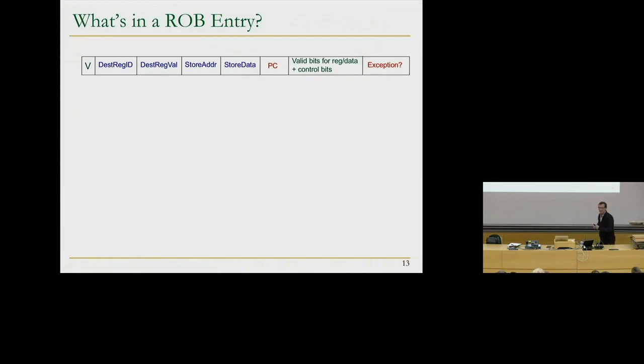Okay? Okay, yes? Let's say the first instruction is a load and the second one is an addition. Wouldn't the addition still need to wait until the oldest one is finished? So wouldn't the addition still need to wait for 600 cycles? That's right, yeah. So if there's a dependent instruction, the pipeline stalls anyway. You don't get into this situation if there's a dependent instruction. You get into the situation if the instructions are independent, but they take different amounts of time. Because remember, we're still in an in-order pipeline. If you're decoding an instruction and the destination register value is not available yet, you stall the pipeline. Make sense? We're going to fix that problem later on in this lecture when we talk about out-of-order execution.